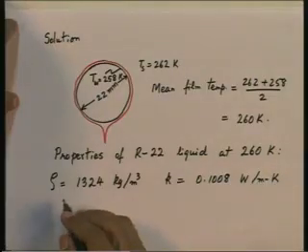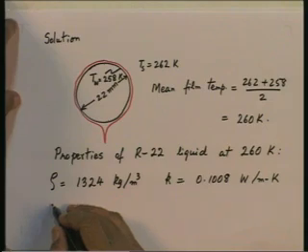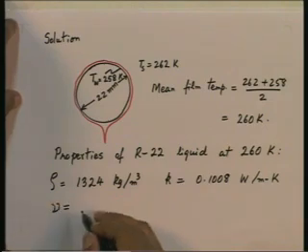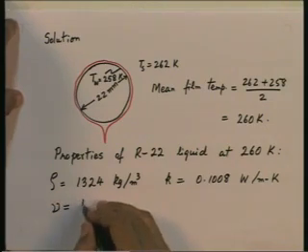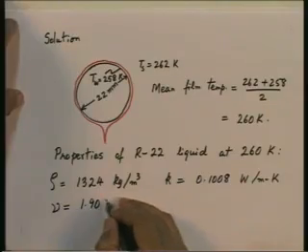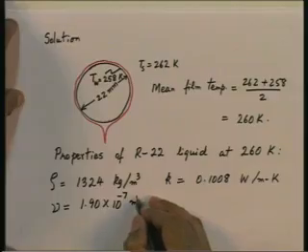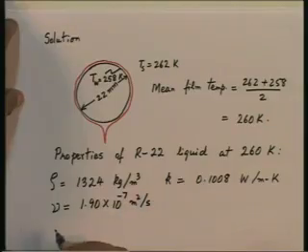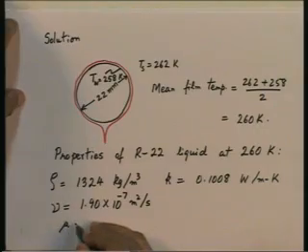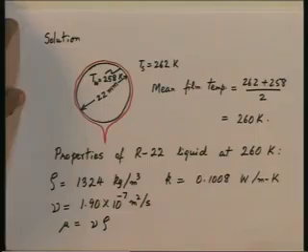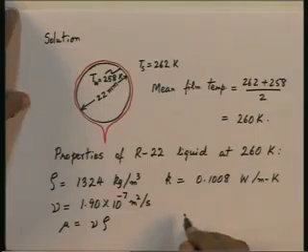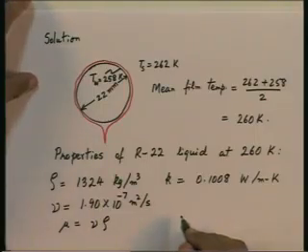You will need the viscosity. In the tables that I looked up, the kinematic viscosity was available. So, nu is 1.90 into 10 to the minus 7 meter squared per second. You can always get mu once you know nu, because mu is equal to kinematic viscosity into density. So, these are the three liquid properties we will need.